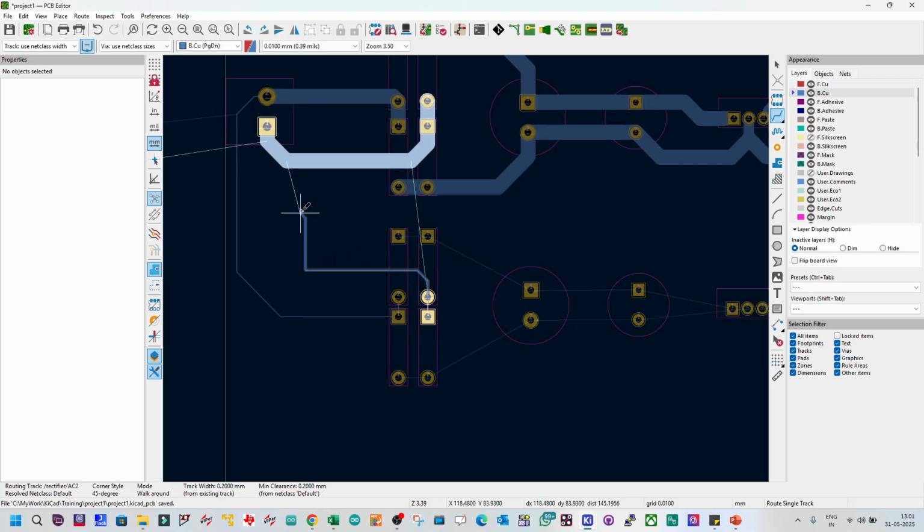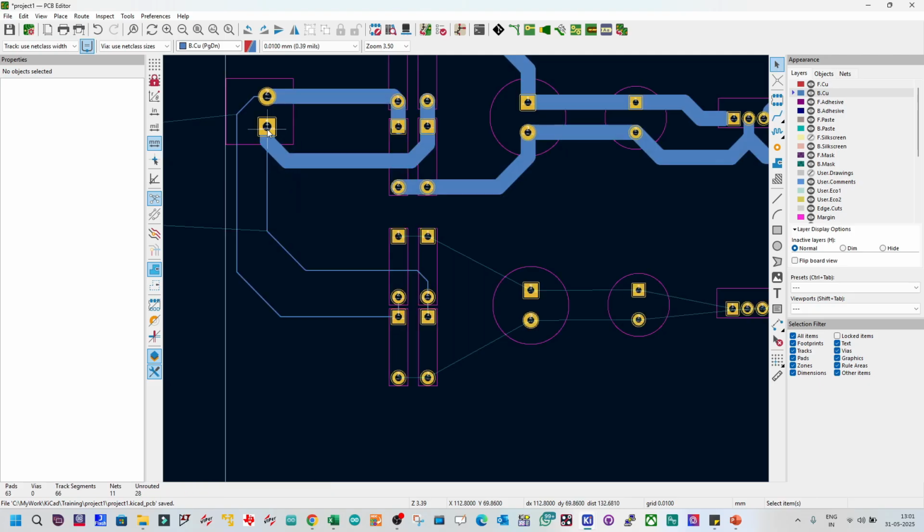The idea is always to take the input from the connector. You understand what I'm saying? Let us not take input from in-between or from these diodes. Otherwise, you will be loading these traces, and they will have common mode noise. Okay, fine. Do not get confused with that one.